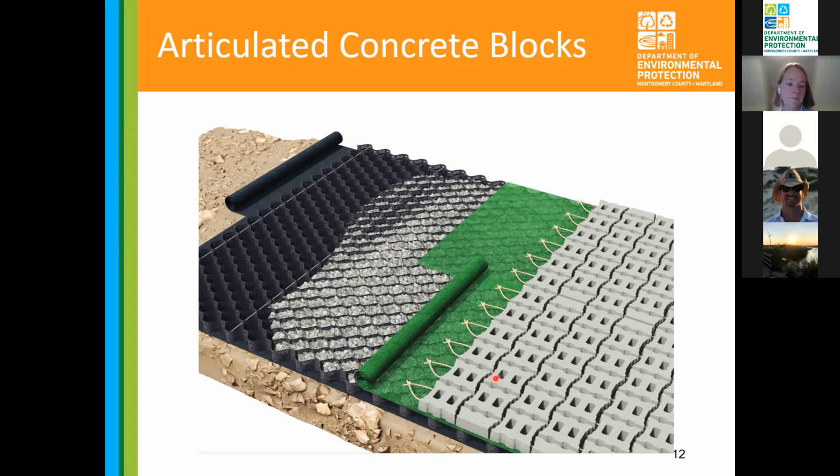So we did perform an alternative analysis earlier on in the design process, where we looked at a more structural astroturf, or even providing gabions, which were the better of the options, but did not provide adequate protections. So ultimately, through conversations with the county and the MDE Dam Safety, we came to the consensus that the articulated concrete blocks were the method of choice for handling the parameters associated with the design event.